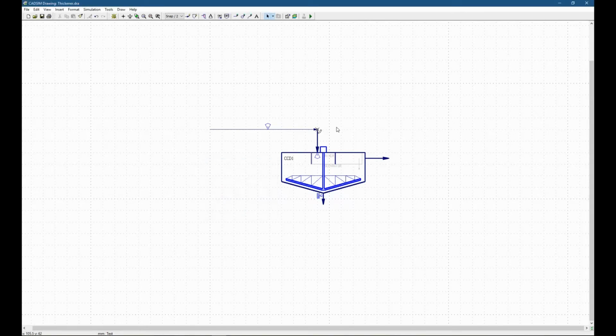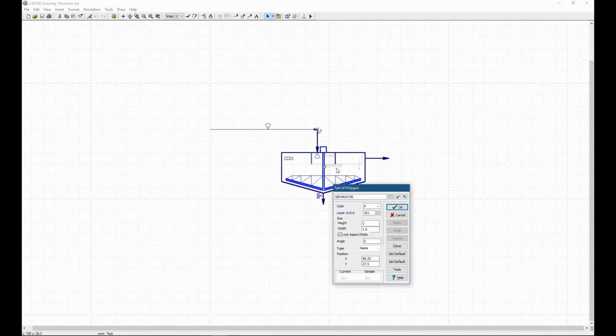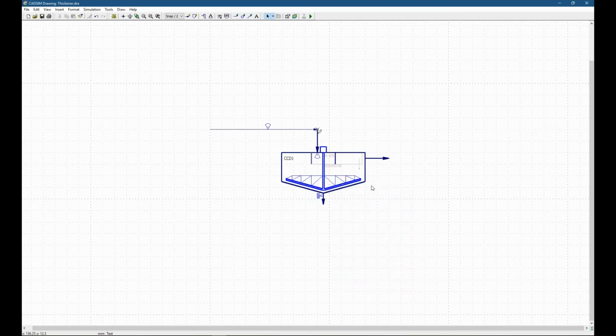The current default module for the thickener consists of two polygons, namely a mixer polygon and a separator polygon. The names for each of the polygons are given in grayed out fonts belonging to layer 101, which is made invisible during simulation mode. The mixer polygon takes on the role of the feed well, where effective mixing of the incoming slurry with flocculants and dilution streams occurs before evenly distributing the flocculated feed over the entire settling area of the thickener. The separator polygon will split its components, in this case water and hematite, among its outlet streams according